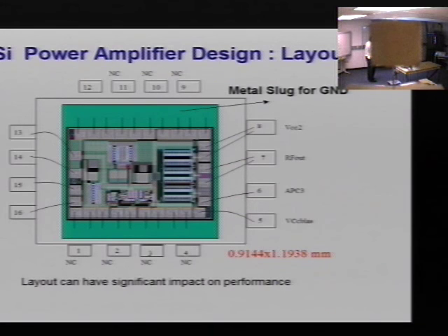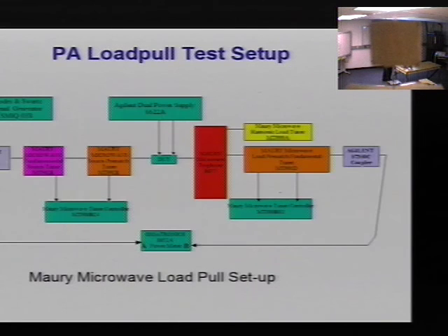One of the layouts. Did a lot of stuff, but basically showing you that there's a large number of grounds that are used, very critical, and using the down bonds is very, very important. And the layout itself can have a significant impact. There's a lot of art involved in doing the layout and understanding what the detailed parasitics are and how each device behaves differently, because not everything's in a symmetric environment, and one really has to think about how to design in that. I think it's a very, very critical area.